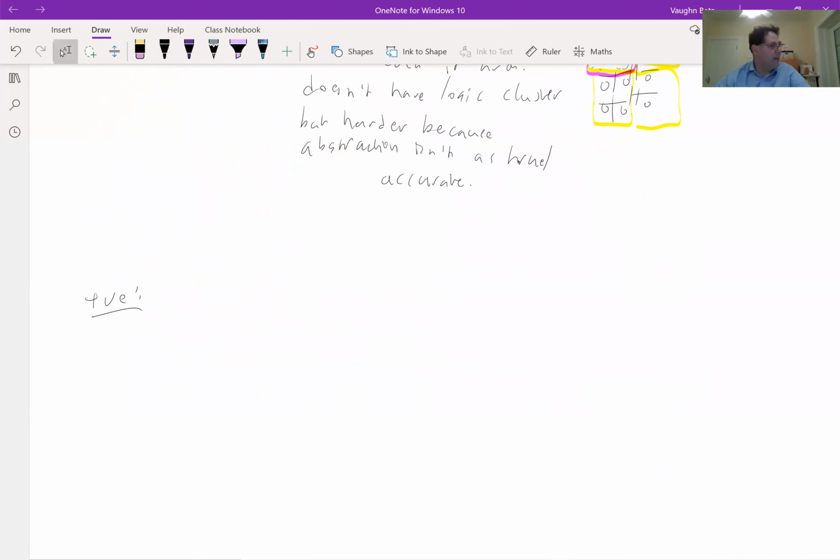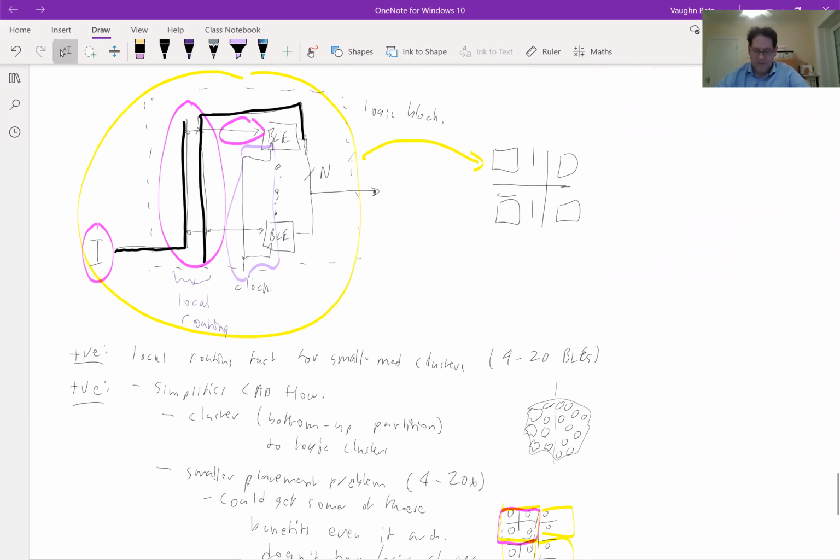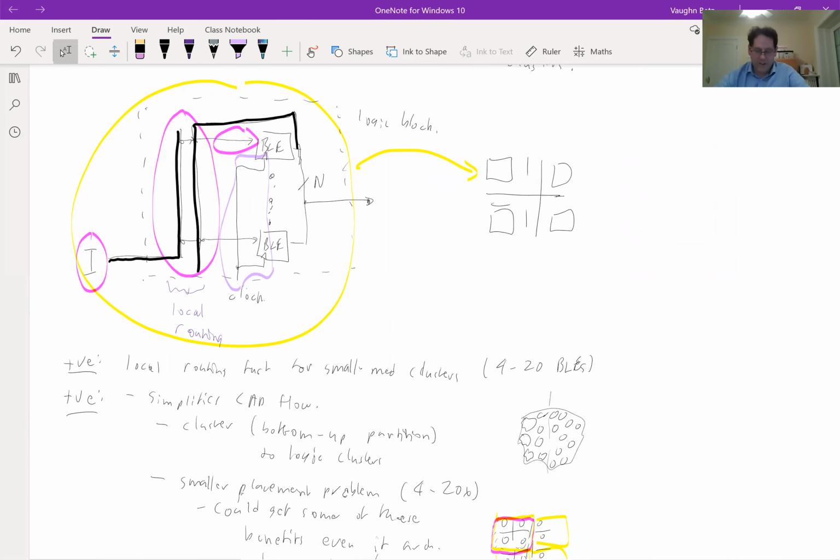Is that a good idea or a bad idea? Why did I do that? So any thoughts on this? Think of any reason why I drew the clock differently? Okay, so Camilo's saying a good idea, the fan out skew is decreased. Yeah, I do want low skew. So basically by keeping this clock simple, making sure it's got the same wire, basically everything, I'm going to reduce clock skew. How common is it that I need a different clock to every flip-flop?